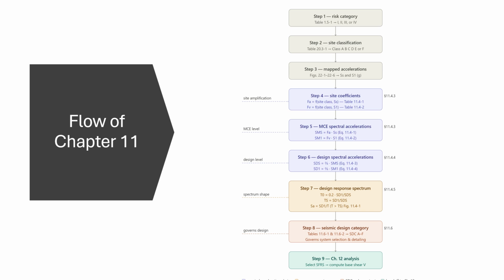Kind of resource. I'll link that in the description below, just if you're not familiar with it. So site coefficients, and then you have your spectral accelerations. This comes from chapter 21 as well. This can get pretty complicated, but long story short, this depends on the rate at which you're designing for the ground motion values.